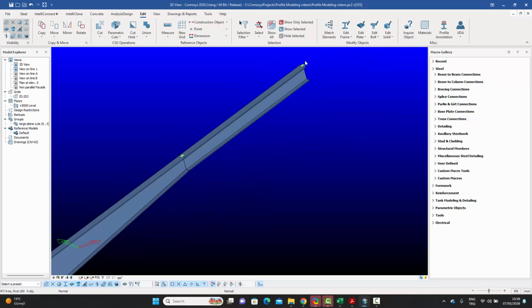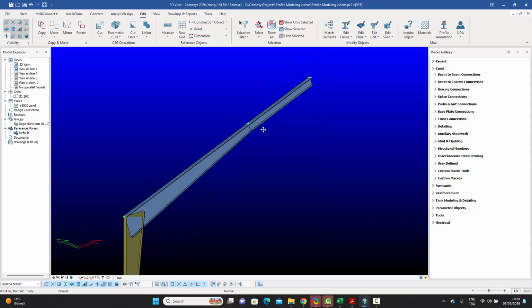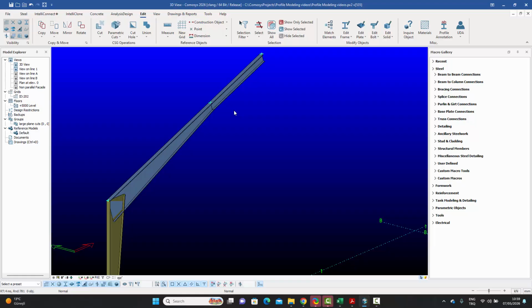And we will get the I-beam. Since this is symmetric, we did not need to do the Control Q. If we press Control Q twice, we'll give it the same coordinate system as the other one, and maybe that could be preferable in some cases, but it would work both ways since it's not really an issue.